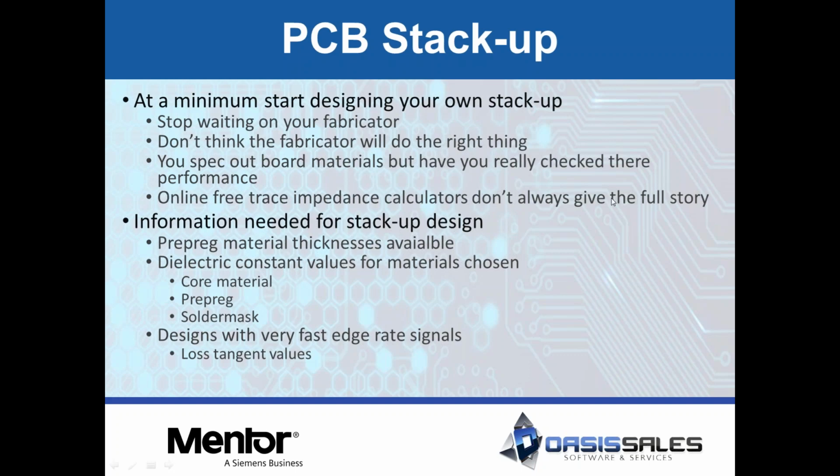So the online free impedance calculators, a lot of people say, oh, I just use one of those to calculate impedance. Well, it doesn't give you the true story of the impedance of that net. It may not take into account all the fabrication processes that happen, the etching, etch back, solder mask over the top of a trace changes the impedance. When you're doing a stripline structure or a microstrip, obviously the materials, how close you are to planes. You can play with a lot of that stuff with the free tools, but you just can't get the full story from that unless you use a real stack-up editor application.